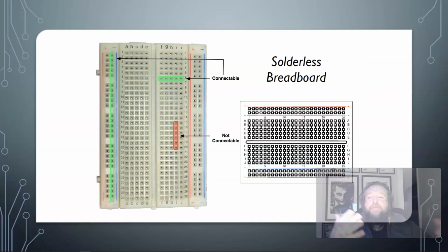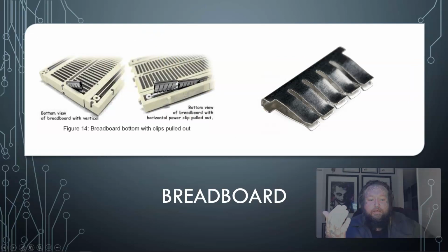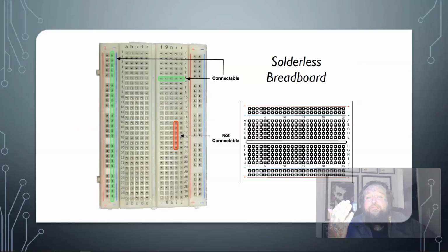What's important about that is, when you look at this breadboard here, you'll see these little lines and think, okay, it looks really weird, but I have all these little holes, and that's where you're going to be plugging in the actual wires. Then you just have to know how the electrons will flow. There are always common rules. This row that we see here, where it says 1 and we have A, B, C, D, E, and this row right to here, 1, 2, 3, 4, 5, these are all connected together.